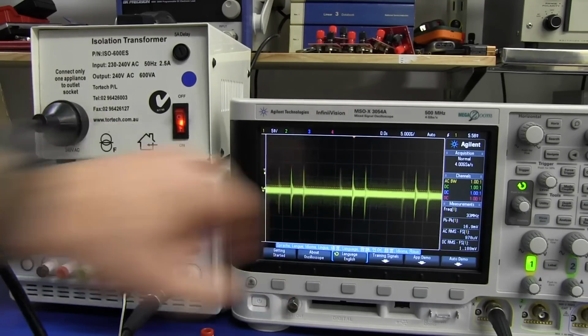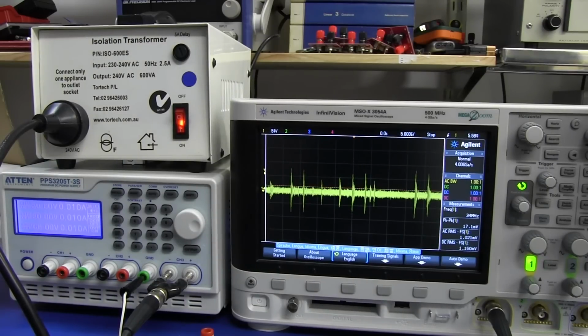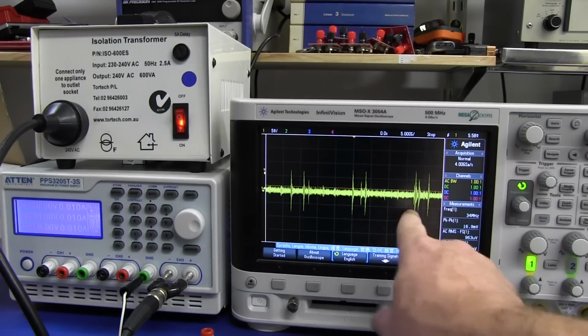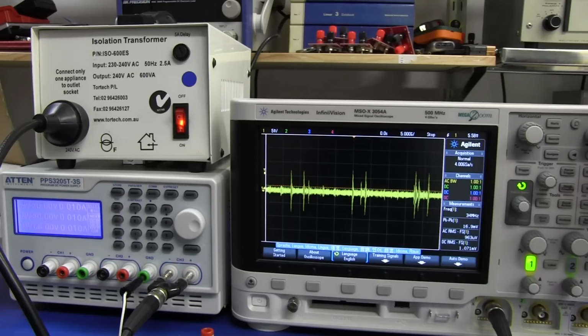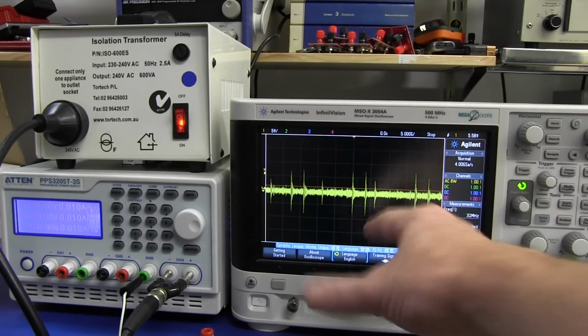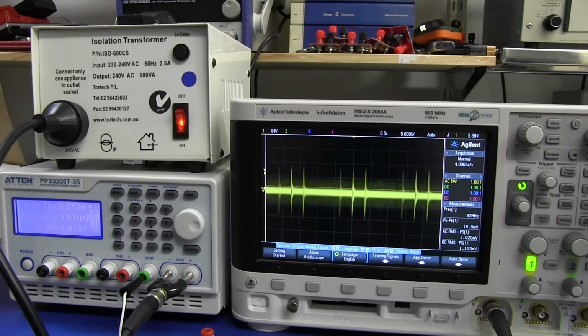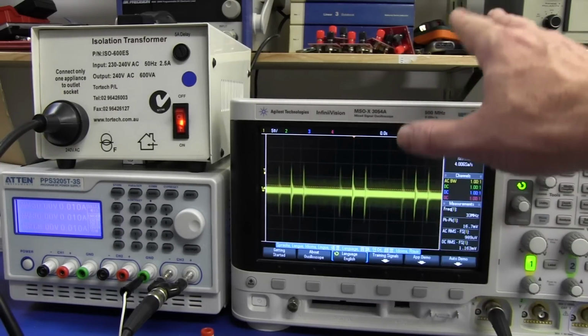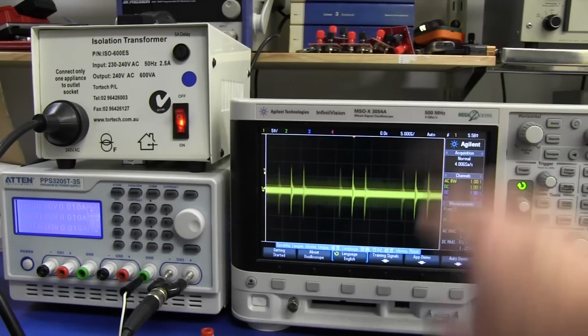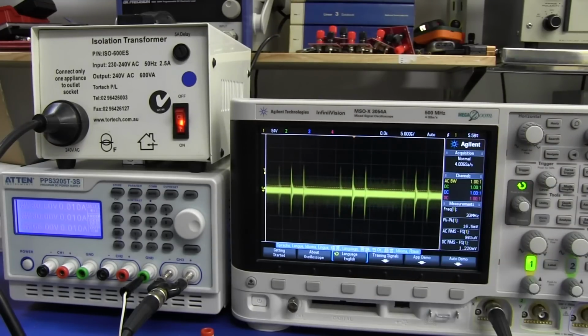But look, it's physically changed. Now, it's still there, but it's different. We've got different components picked up. We're still at 5 microseconds per division there, but it's not that consistent 66.6 kilohertz we saw before. So, we're getting closer to this thing, and you'll see that it'll instantly go back. If I plug the proper mains cable back into this thing, it'll instantly go back to exactly what we saw before. So we're tracking this thing down.